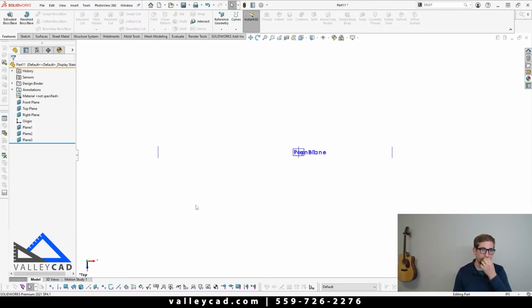So as I'm modeling this, it's a really good practice to make it so that your origin is centered about your weldment structure, because then you could utilize mirroring and linear patterns. For patterning instances, it's really powerful to model this way. Now, as we look at this, I need to make it to where my model bisects this. So I'm going to create global variables, and these global variables are going to control my overall length, my overall width, and my overall height of my conveyor frame.